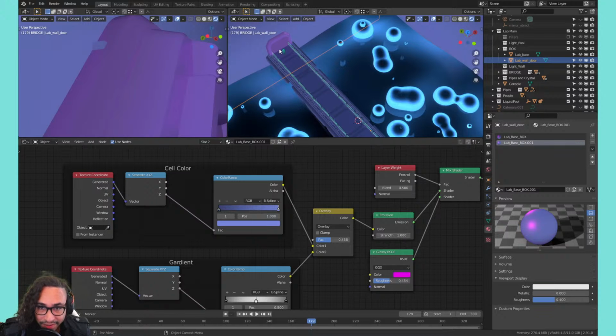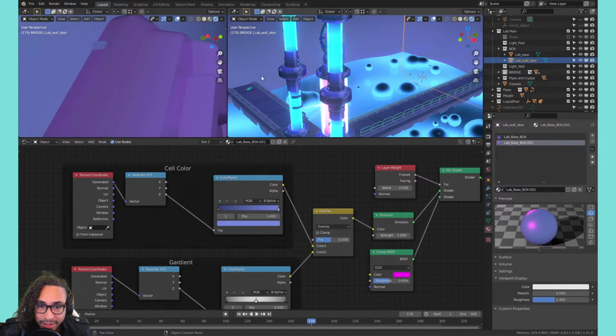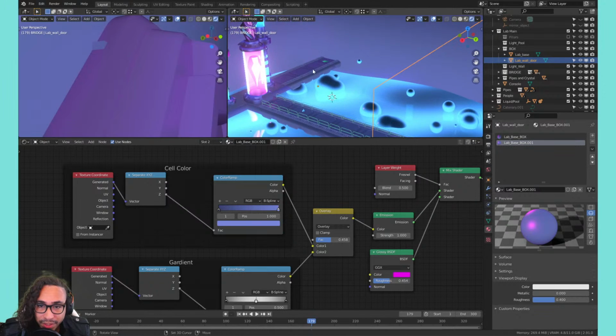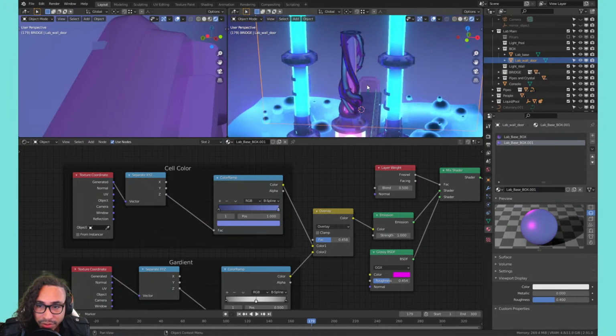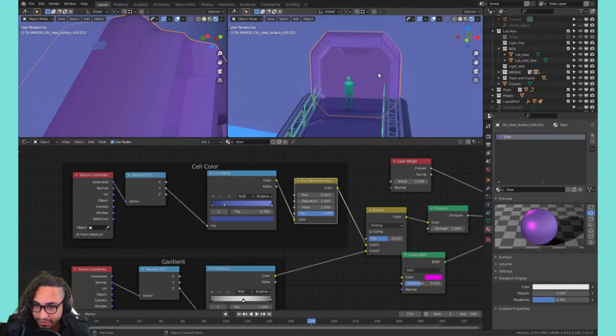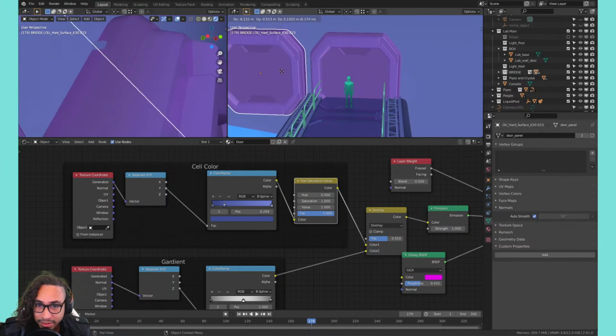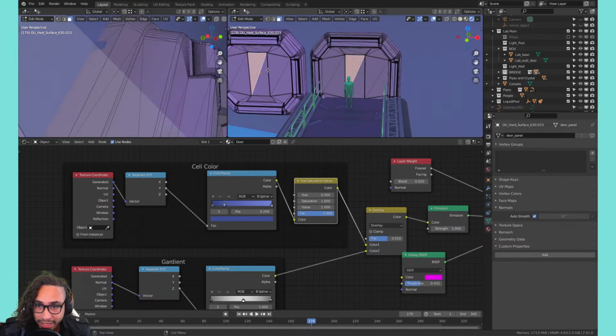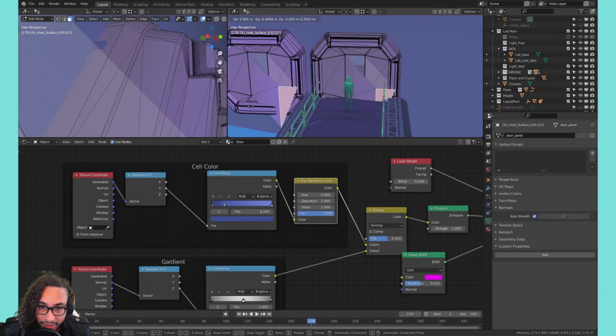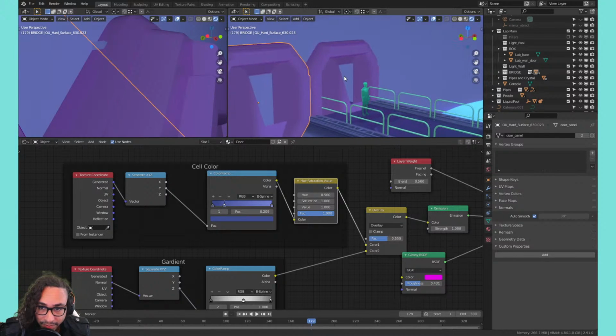Now that I have this door, I think maybe these sides will have doors. It definitely looks weird that the thing goes into nothing. So I'm going to duplicate it, but this time instead of doing Shift D, I do want it to keep using the door panel mesh, right? So I'm gonna do Alt D. So that's an instance. So once again, if you go to edit mode, you see that it edits both of them. If you do something crazy, you see that both of them have it.